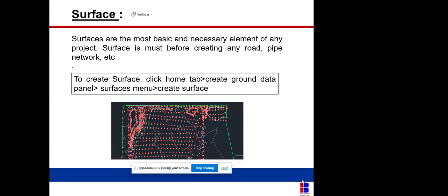what the surveyor will do is go to site, establish the boundary of those estates and do a detailed topographic survey of the area. The town planners and co would have done their layout for the estate and planned their road network, and where the buildings will be situated. Once you have established that, you import your points, then you use the layout superimposed on the drawing that you're working on. From there, you create a surface for the particular estate.